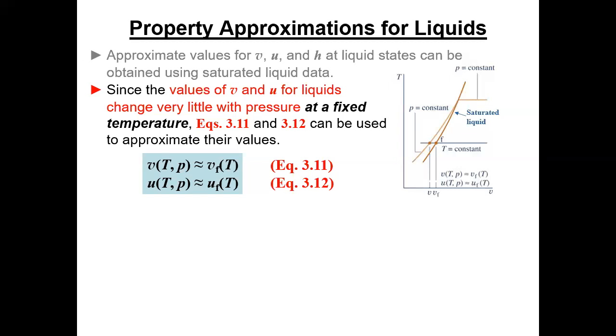So let me go to 1,000 psi. So, you know, the saturation pressure is 67, and I'm going to put 1,000 psi in my calculator at 300 degrees. I'm going to keep it right there. And on the internal energy, it's off by 0.47%. Less than 0.5% error. And it's 900 and what? Is that 63?